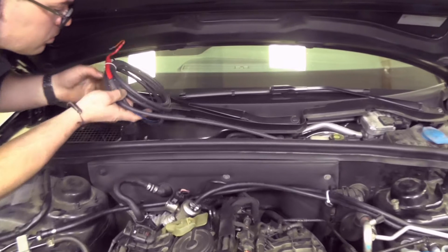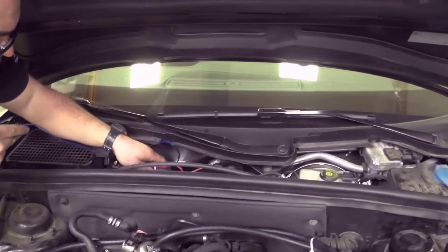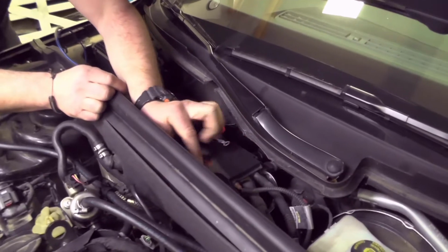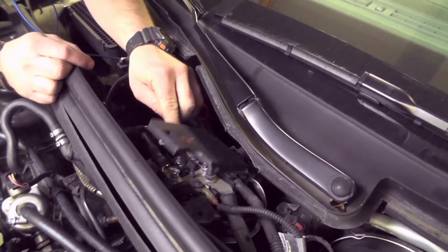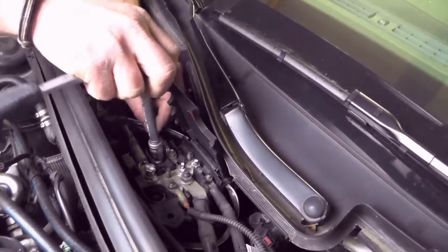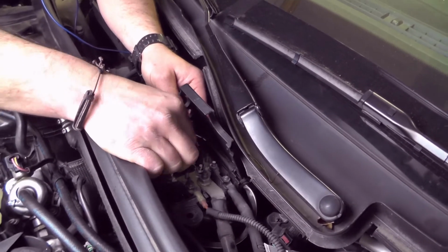Check which terminals are permanently powered and which are switched on by vehicle ignition before connecting the main cable to the power terminal. Then connect the red wire to a plus 12 volt terminal.